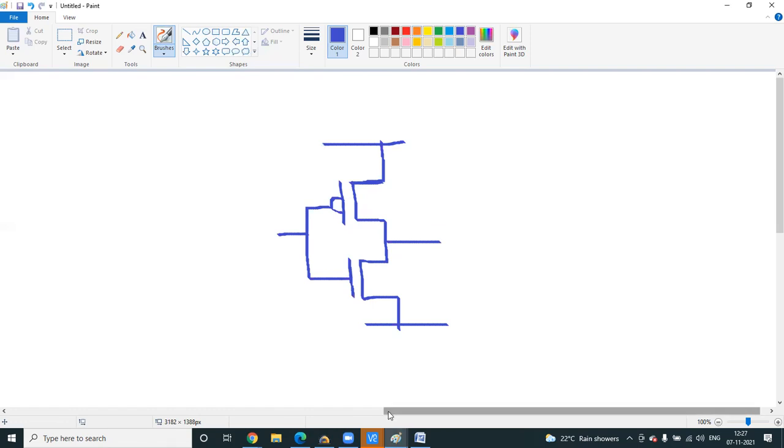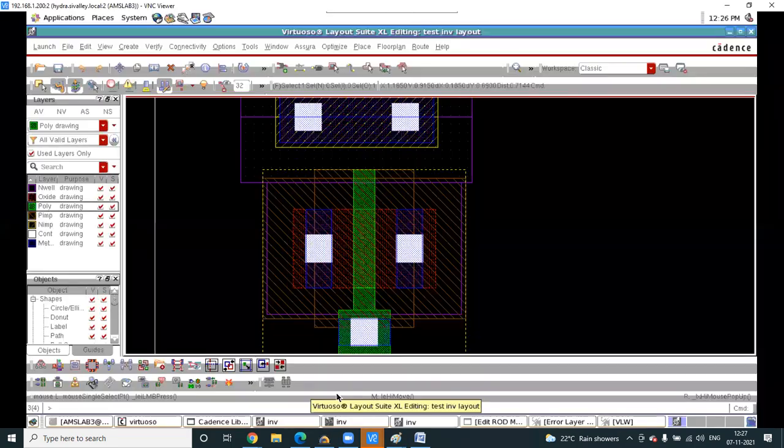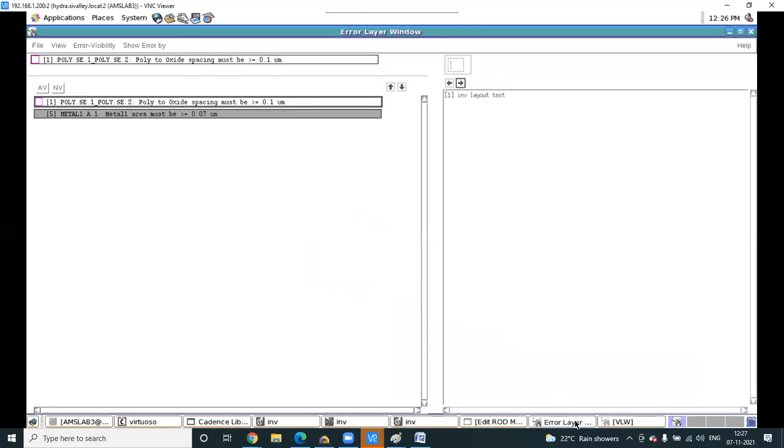Okay. But it is mentioned as oxide. Some books like some layer technology you will find that is diffusion. They will not mention oxide also. OD layer. Okay, so here in this technology they are giving oxide layer. But this is like an active region. If you see in your DRC, whenever it is oxide is asking, it will show you the active region also. So don't confuse, this is an active region.